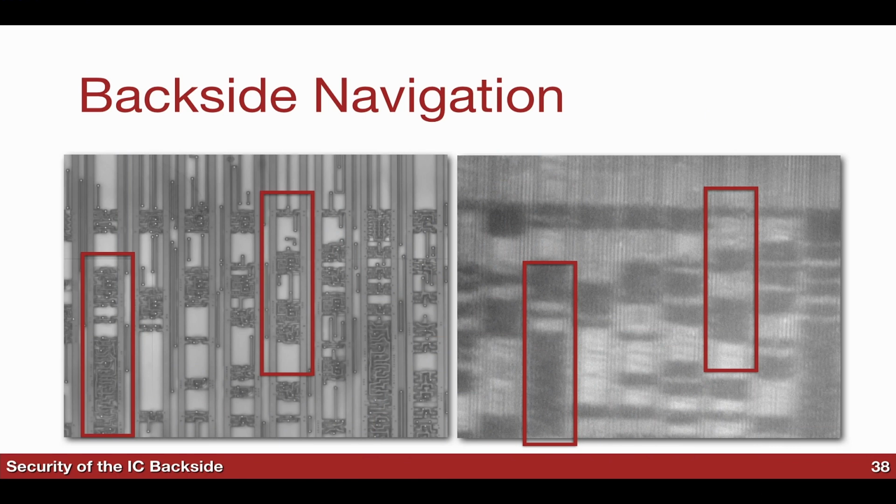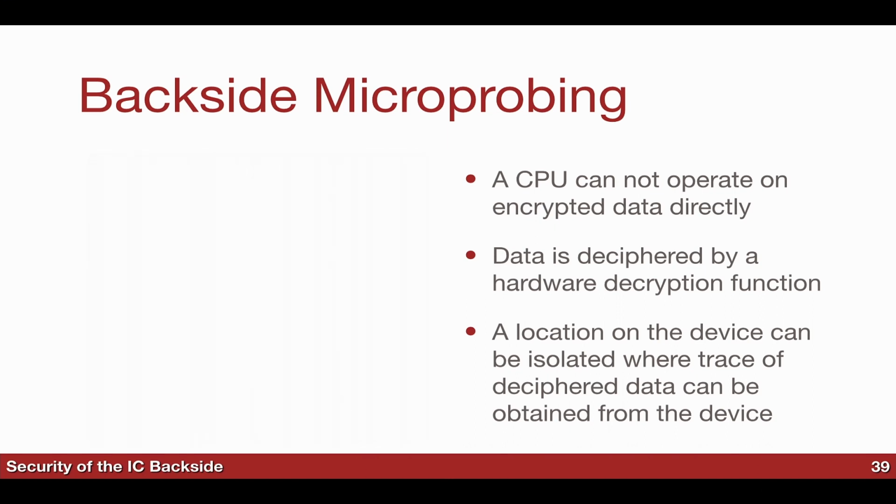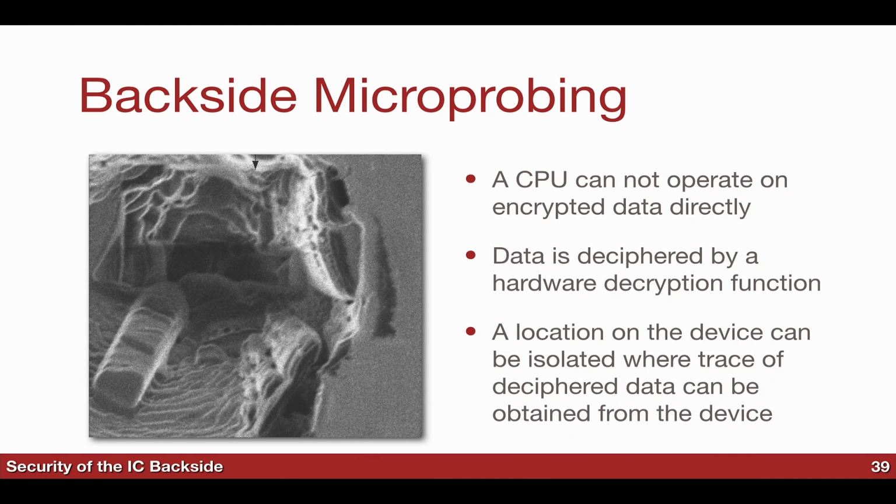Now we find where we want to go, and we start making the trenches, which is exactly what we have here. The wire we're actually targeting, as far as I remember, was metal 3. The transistors go up to metal 1, then there's metal 2 and metal 3, and there was something connecting between 2 gates, and this is where we're targeting. So we're effectively going through 3 layers of the device to probe it. Now we deposit some metal, which you can see is the conductor, the bar coming out.